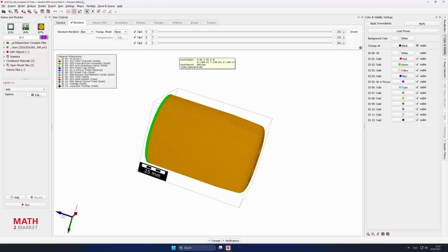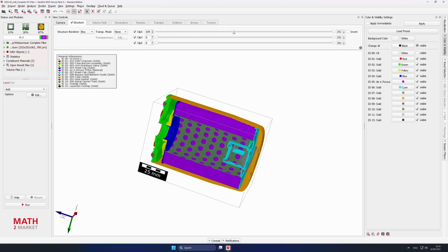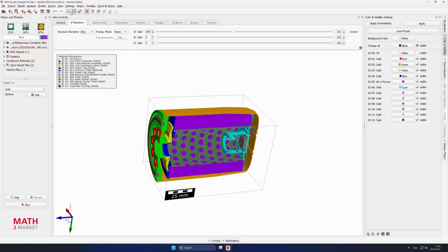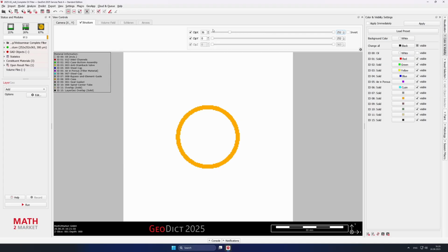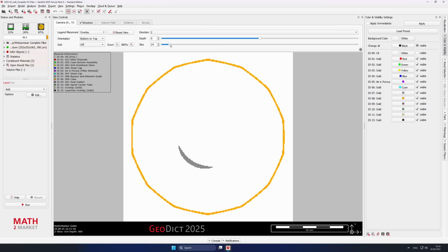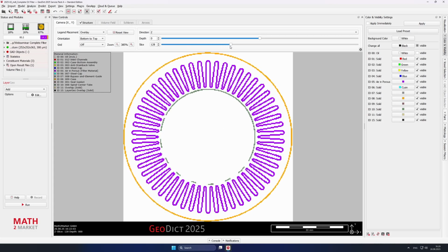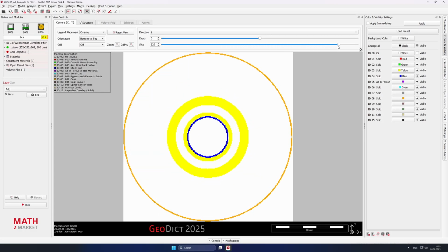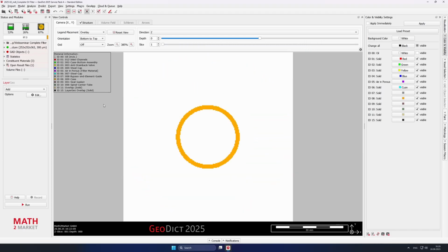And as you can see now, if we click in the structure itself, we have the material in there. And for a sanity check, you can also go for 2D in there. I will undo the clipping, and you can then slice through the structure, and you can see it matches perfectly to the old position in there. So there's no overlap, and it works out perfectly. As you can see now, we have the materials in here.